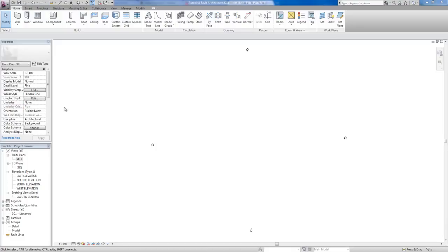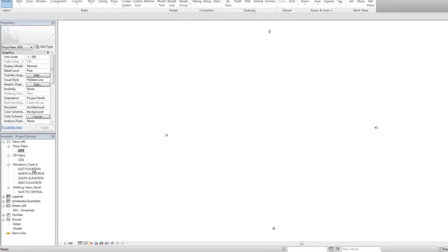Alright, so when we open Revit, you can see we've got our blank workspace here. Now it doesn't have to be blank, you can already be working on your project, and maybe you want to bring in a DWG of toilet blocks or whatever, so that you don't have to draw them in 3D. That's fine. So just as long as in your project browser over here that you're actually set up in the view that you want to bring the 2D file into.